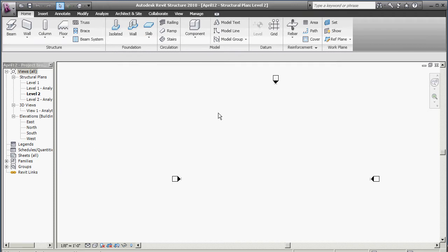Alright, we're working here in Revit. We're going to show you once more how you're going to pull in the campus drawing by using links, and that document is available out there. We are starting in a project and renaming it right away to something saved, at least if you're working by yourself out on your H drive, though you'll be referencing a lot of things potentially off the K drive, but you could also pull them local into a drive.